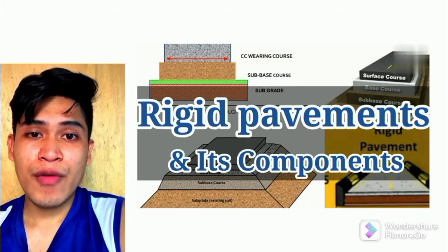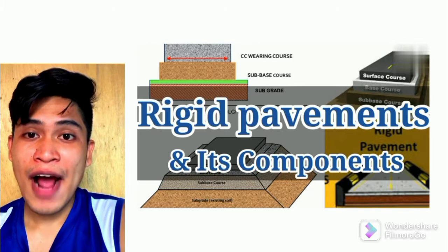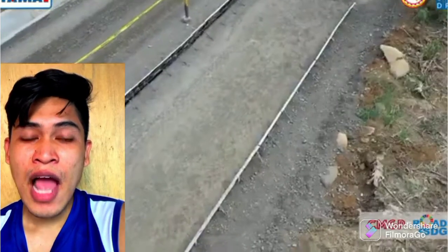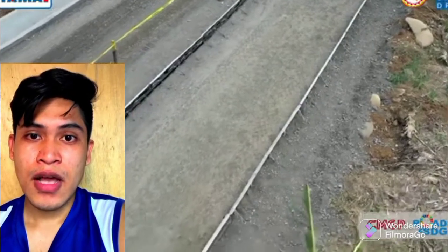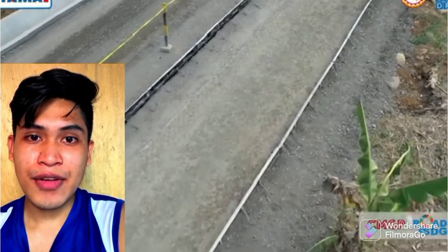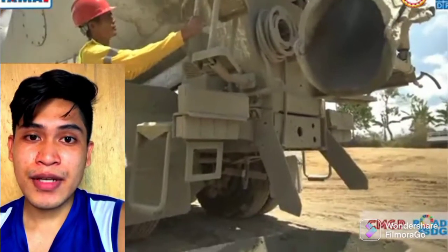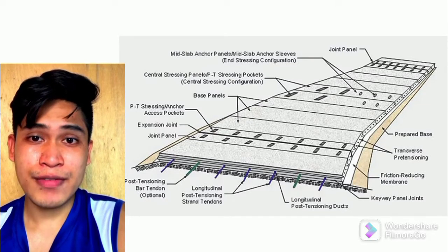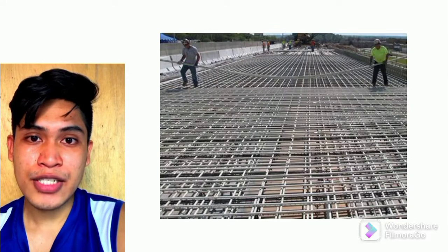This consists of a reinforced or unreinforced in situ concrete slab placed over a thin granular base course. The inflexibility and strength of rigid pavements enable the loads and pressures to be dispersed over a wide area of the subgrade to reduce the potential impact.